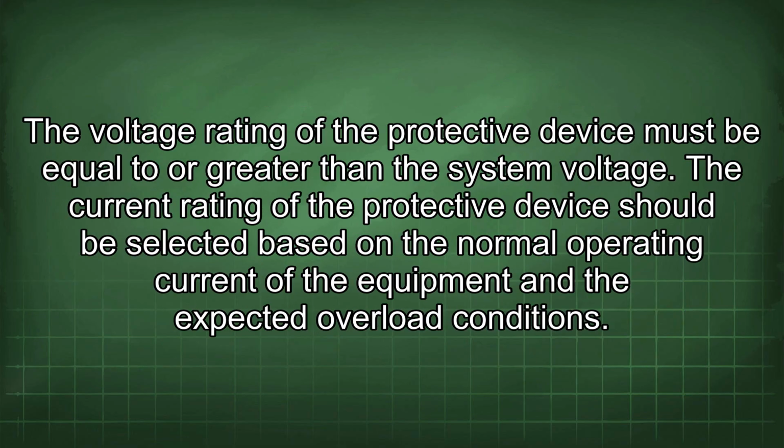The voltage rating of the protective device must be equal to or greater than the system voltage. The current rating of the protective device should be selected based on the normal operating current of the equipment and the expected overload conditions.